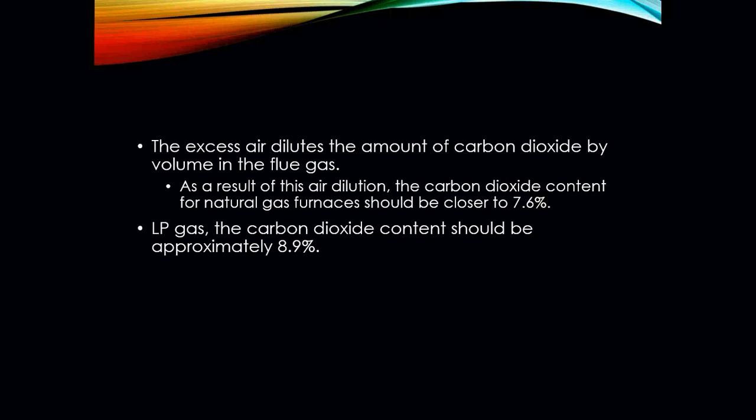So as a rule of thumb, when we're taking a combustion efficiency reading, we're looking at somewhere around 7.6% for carbon dioxide on our measurements. LP is a little bit of a heavier gas, so that carbon dioxide content is going to be a little bit higher. For practical combustion, we're looking at somewhere around 8.9%.